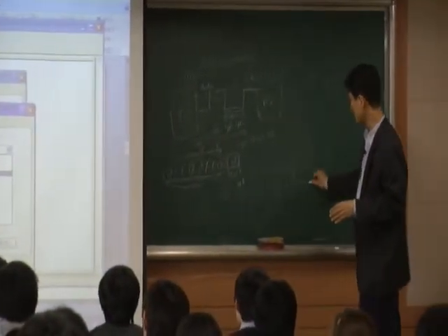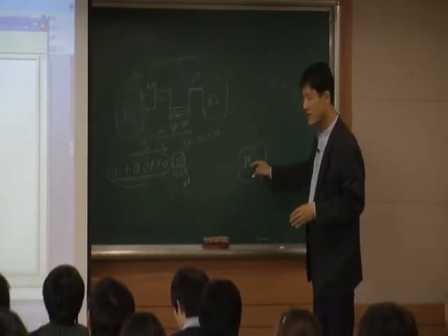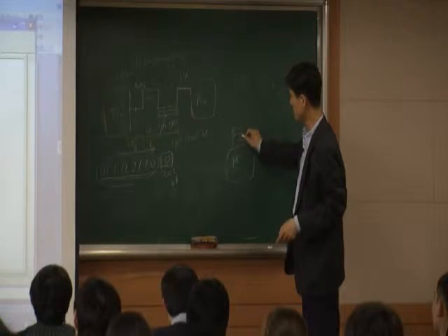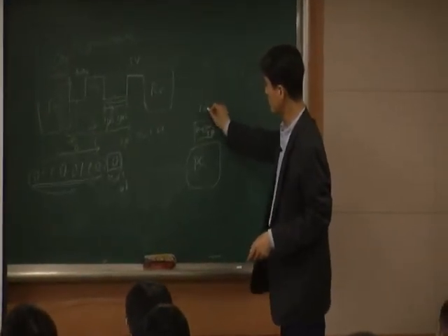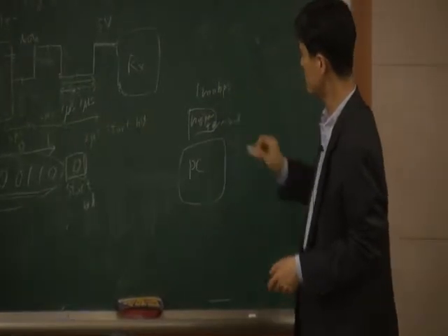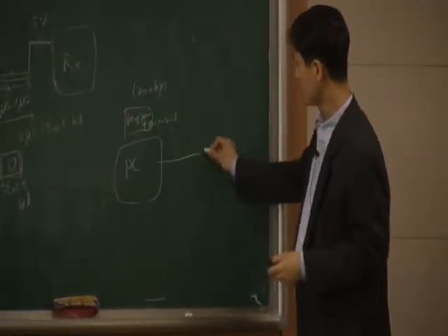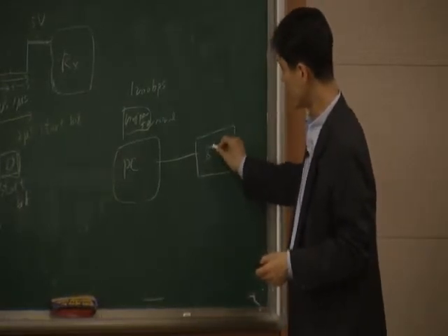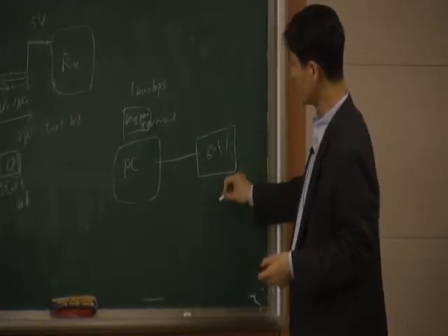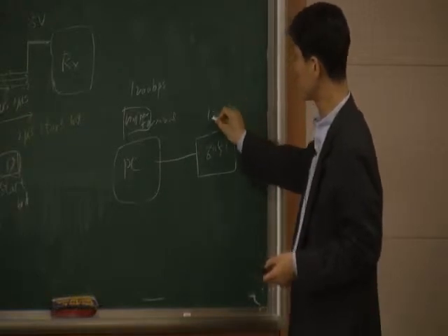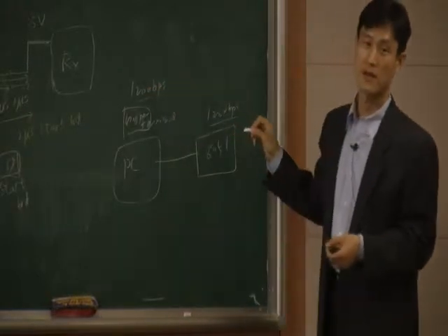So you have a PC here. In the PC, you can run the hyperterminal like this. This is called hyperterminal. And in the hyperterminal, now you set it to 1200 bps. And the PC is connected with our processor. And inside here, we also have to set it to 1200 bps. We have to make it the same.